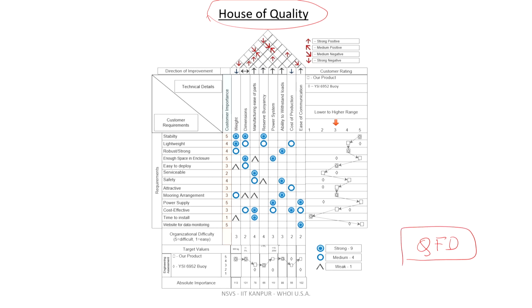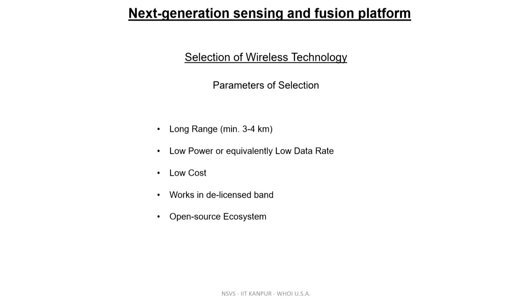So, using QFD you can actually fill up this house of quality, where on your left side you have all the customer requirements, and here the customer rating is established by giving scores against each one of these parameters, and here it is showing its correlationship with the manufacturing, so that you know how much your decision is entangled with the manufacturing decision.